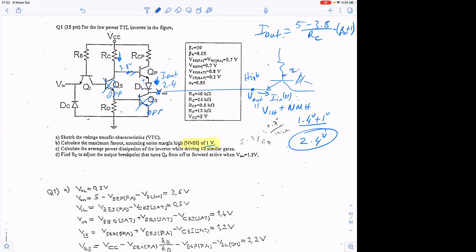This was 3.2.3, I guess. So I find this current, and then that current times beta R, I in prime, is equal to beta R times the I base prime current. And the I base prime current is equal to 5 minus 2.3 divided by R base. So you don't need to literally lose time here if you did enough examples. Is that okay? Yes, sir.